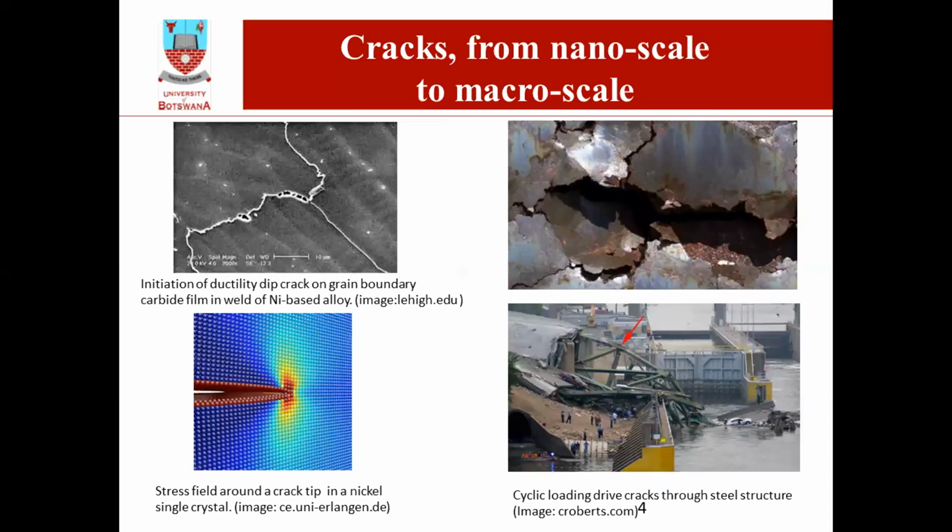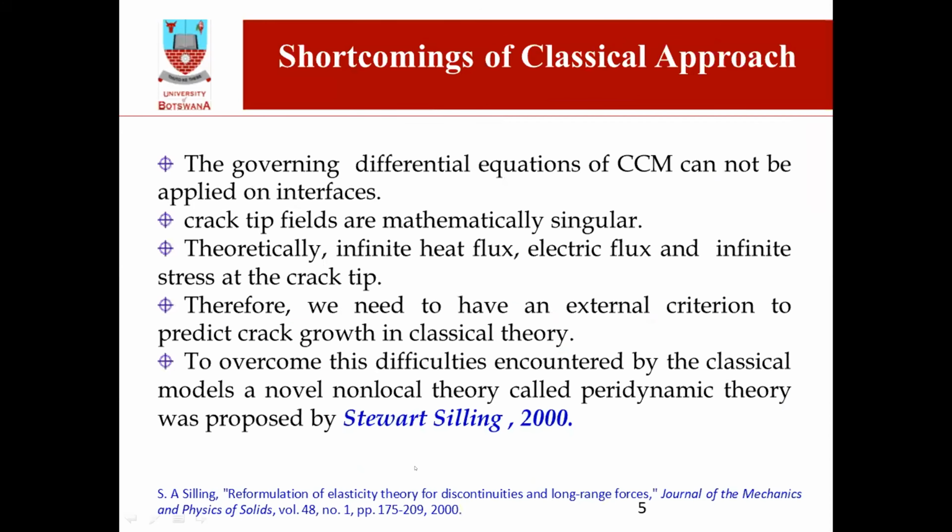So the main idea behind peridynamic theory is dealing with discontinuities from nanoscale to macro scale. This one is the nano, and this is the macro scale. Some of the shortcomings of the classical continuum theory is that the governing equations are partial differential equation based, so they are not convenient in dealing with discontinuities like crack tips, maybe faces, and so on, because these things are, mathematically speaking, singular.